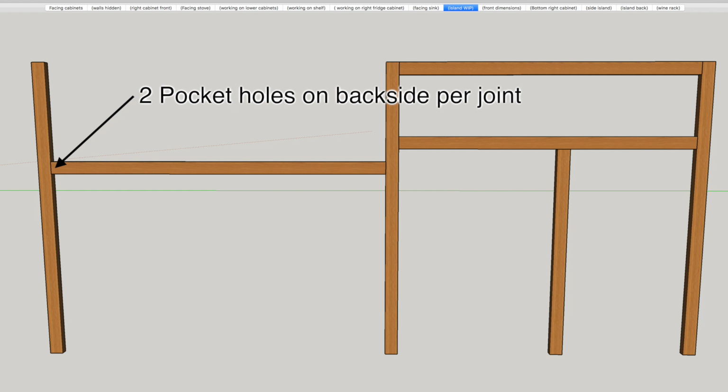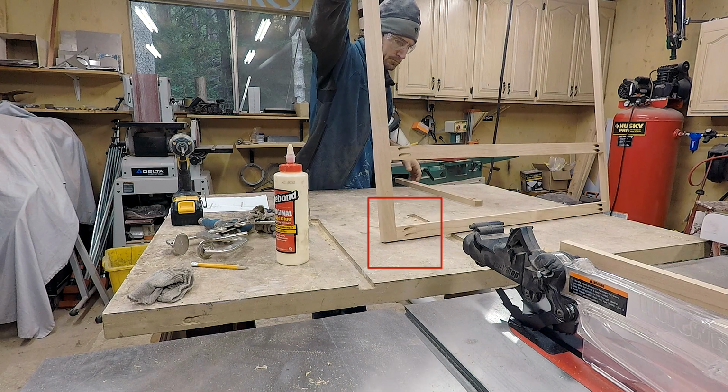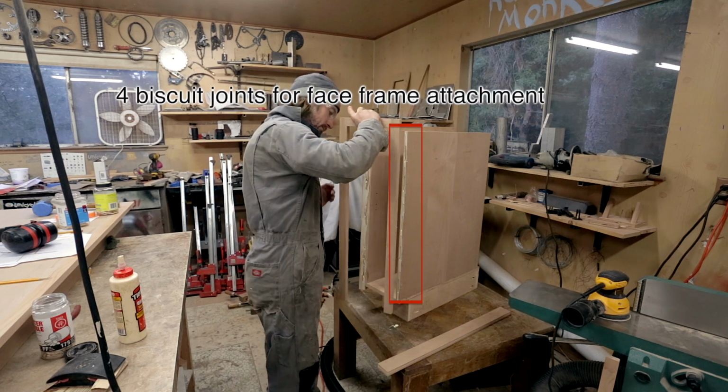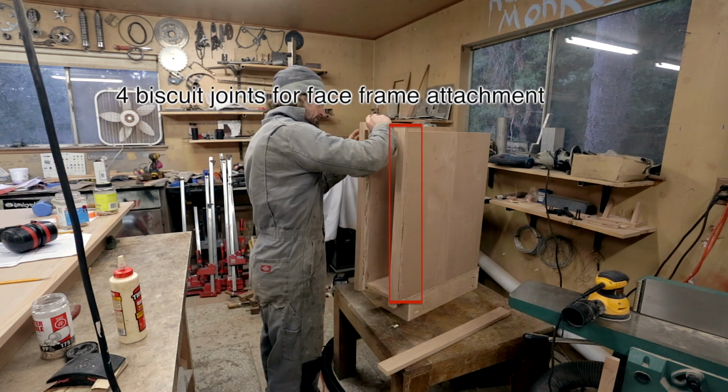The face frames themselves are attached together with pocket hole screws. I use 2 screws per joint, and it's pretty simple to do and quick. It also allows me to assemble it without any clamps, and it can glue up and I can do other stuff. Then the face frames themselves are attached to the whole assembly or the whole box via biscuit joints.